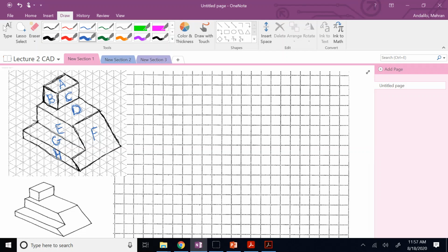And remember that this direction here is your front view. This direction is your right view. And if you look from the top, as you are staying on the front side, that is your top view. Okay, so we start with front. Let's say we start with direction instead of planes.